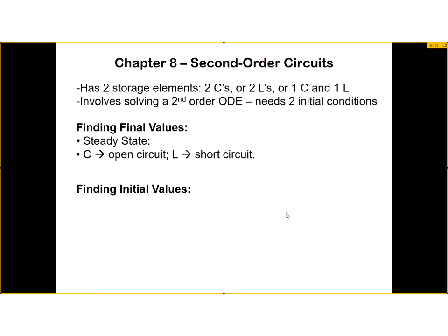Now, in terms of finding initial values of variables, usually if it involves a capacitor, we're obsessed with the voltage, right? And there are two reasons. Because the voltage of the capacitor determines the energy, and consequently, because of continuity of energy, the voltage in the capacitor doesn't jump.